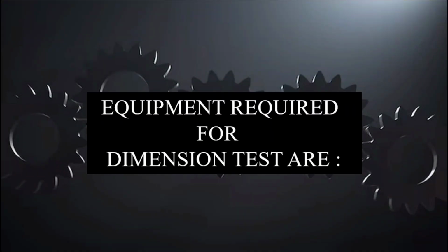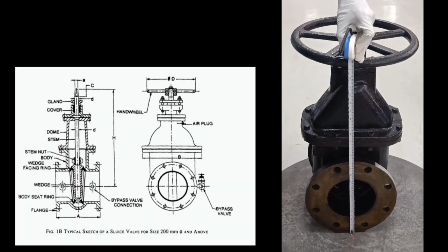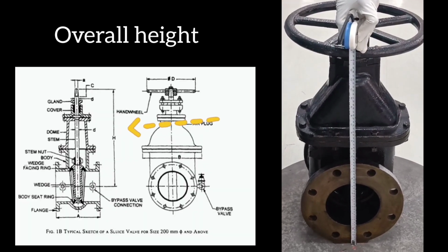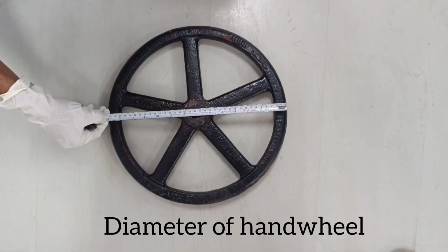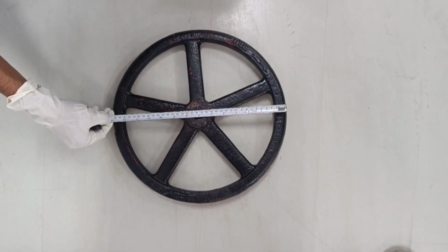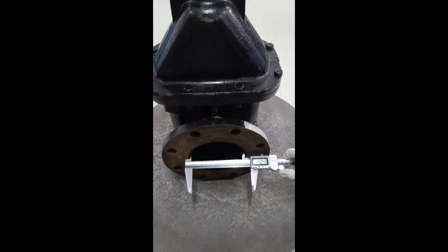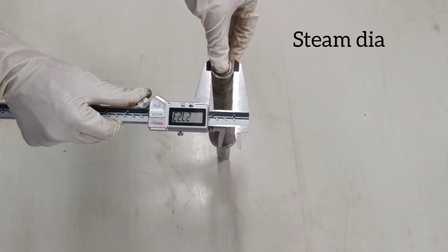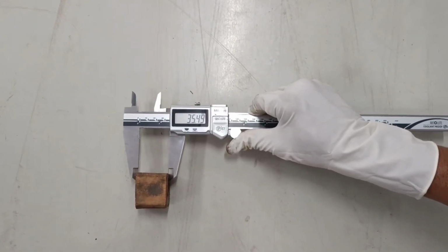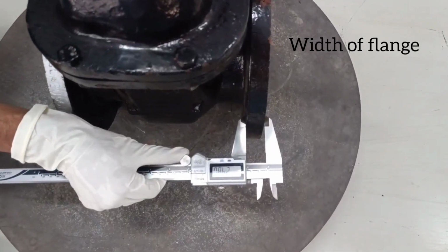Dimension test. Equipments required for the dimension tests are measuring tape and vernier caliper. In this test, we will measure the overall height of the sluice valve, the thickness of the flange and diameter of the hand wheel as per the standards. The internal bore dia, number of bolt holes and the stem dia is also measured as per the standards. Width of the square and width of the flange are also measured as per the standards.